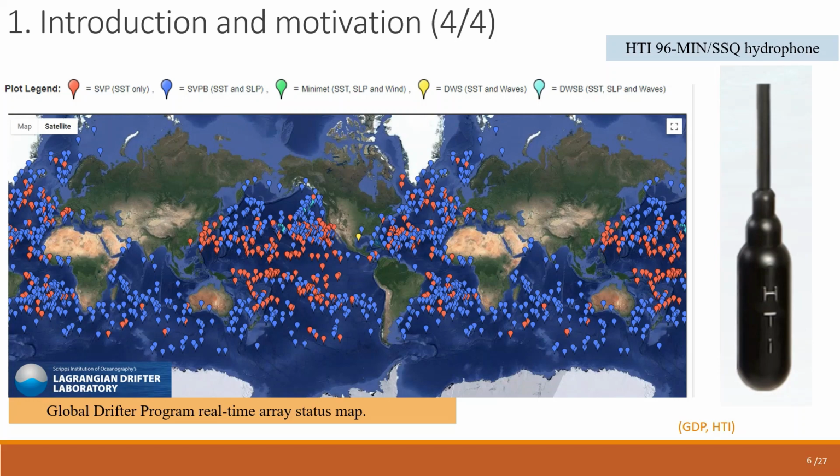Acoustic rainfall gauges provide a simplistic solution with stable calibration characteristics. The Global Drifters program provides scientific data of in situ measurements for a broad array across the world's oceans. If they were to be instrumented such that they could yield rainfall rates over the ocean, that would be a fundamental advance in measurements of rain globally.